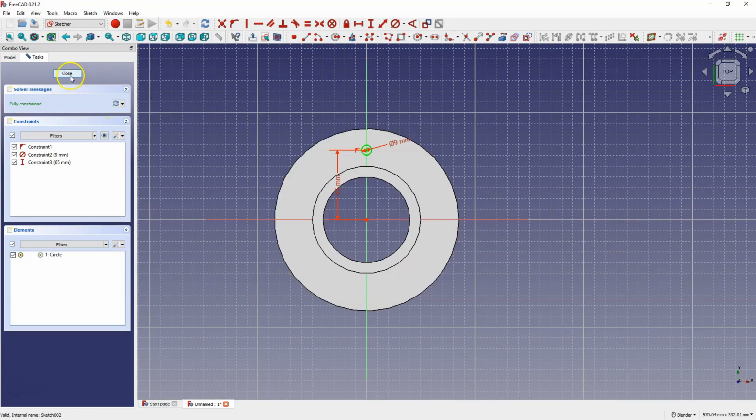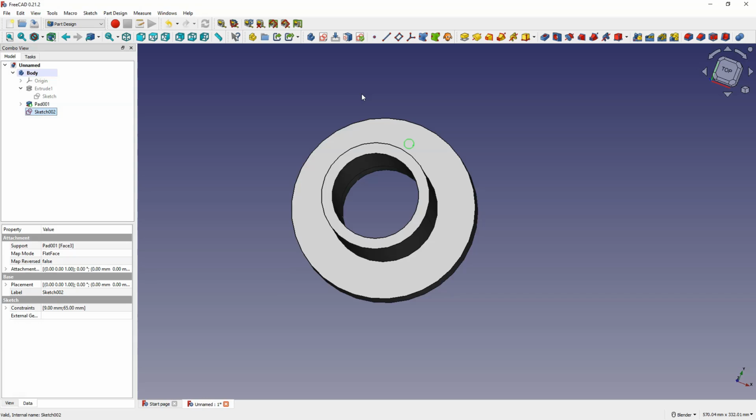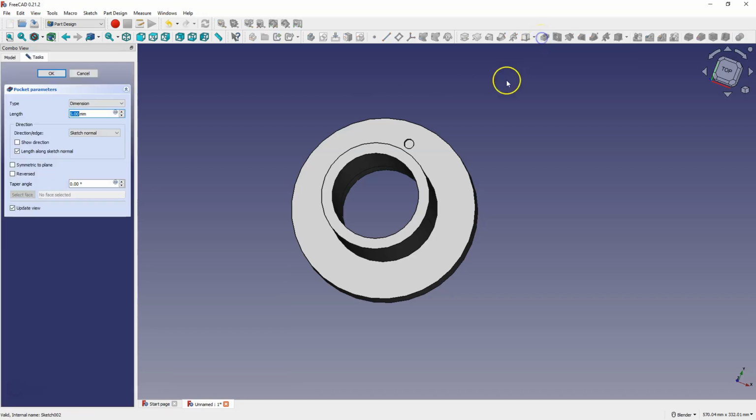Okay, close the sketch and add the next operation, which will create a hole in this solid. This is the pocket operation. Select this operation. And now we define the pocket depth. And regarding the parameter in this window, we can enter a specific value here, but we can also rotate the mouse wheel and the parameter value will change.